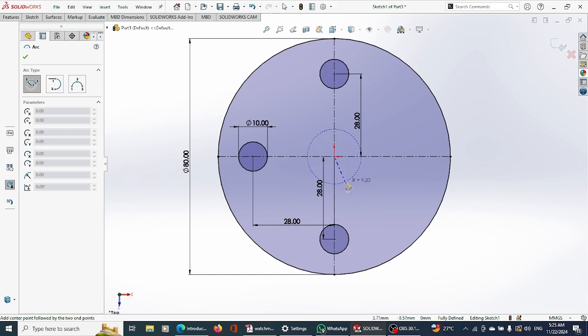Good. Now, you're seeing this line that's going down. If I place this guy here, it means this is where my arc will start drawing from. Watch. You see, you can draw from any direction. You just need to turn your hand around on your touchpad or your mouse, or turn your mouse. But that's not where I want to draw it from. I'll hit escape. I'll hit enter to pick my tool back. I want this to start from this guy.